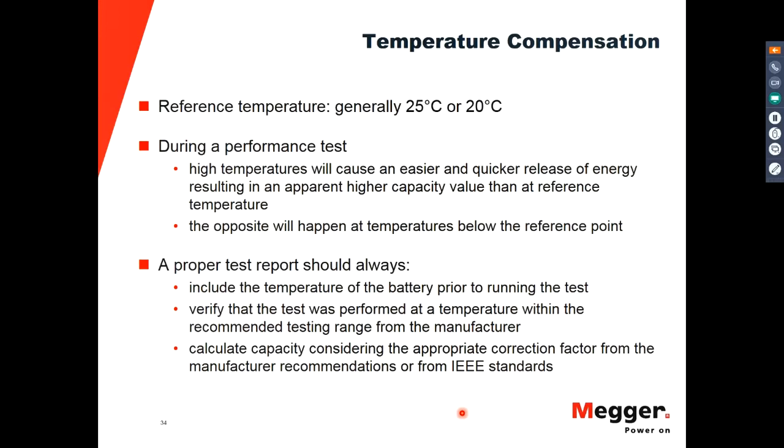Also, when you're running the test, you need to consider the temperature. Remember that the batteries are specified for a certain temperature, usually 25 degrees C. I've seen also batteries specified to 20 degrees C. Whatever it is, you should always get your temperature before running the test. At the beginning of the test, you should know what is the temperature of the battery, not of the room. And then that should be used for the